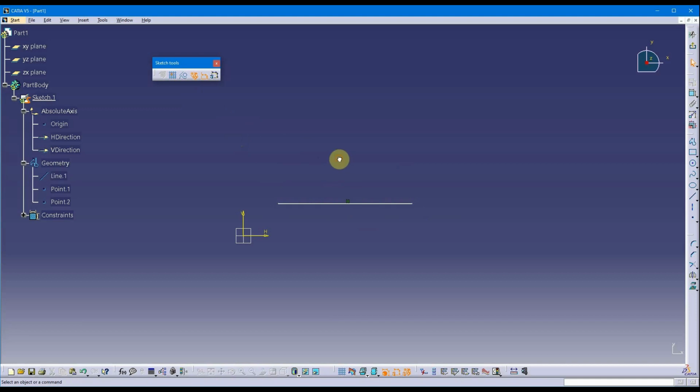So again, if I select this, you get the blue. That means standard geometry. If I select the line as it is, it's construction geometry. So I can toggle this line to be construction geometry, and this is what it would look like. And then I can toggle it back to be standard geometry. Now, we've got a horizontal. That's my first geometrical constraint I want you to know about. So you have horizontal. It's not really horizontal behind the scenes, but I won't get into that right now.